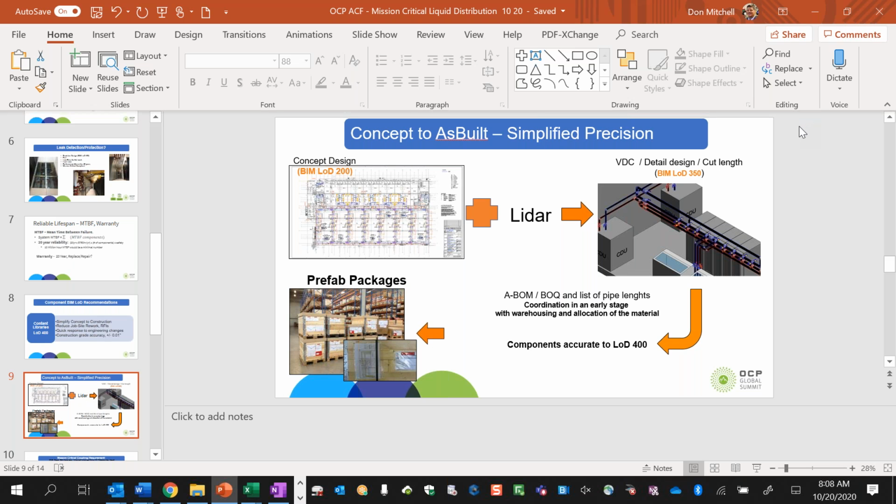So one of the big things that we're talking about in terms of the prefab discussion is, to Don's early point, what are some of the things that can be done to minimize hot work in the space, and also maximize the quality. So when you're talking about piping prefab, one of the advantages that offsite prefab gives you is better quality control for welded solutions.